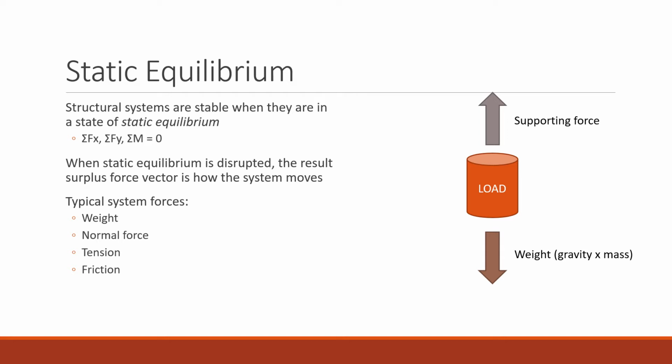This also matters with rope systems, because if you're suspending a load and it's not at a perfect vertical, you've got to balance the forces in the x direction with the forces in the y direction. Forces in the y direction are a little bit more obvious. You've got a brick that you set on top of a table, and the table's resisting the brick being pulled down by the force of gravity. It's in equilibrium in the vertical direction. Then we'll talk about the moment, which also has to be equal to 0. Any rotational forces that are generated away from that given point, those all have to be equal to 0 as well. That can be a little bit more complicated. It matters when systems get really interesting and really complex.